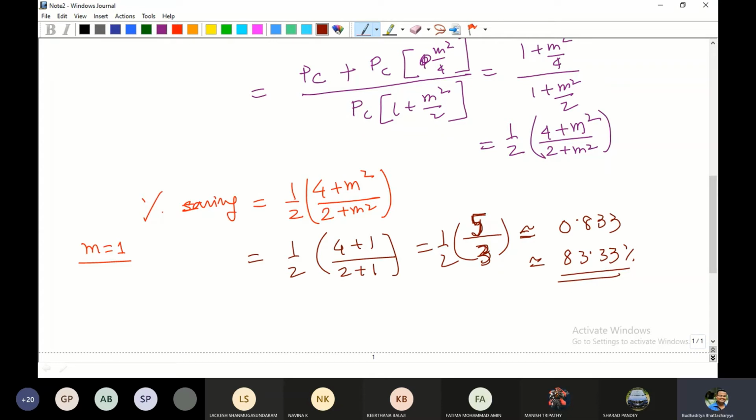Now, in the same process, for DSBSC, which we did last day, it was coming around 67%. This is for DSB I'm talking about. So for DSB it is around 67% efficiency, which is further improved to almost 83% when we are considering similar conditions. So that is why it is advantageous. I already told you about the bandwidth efficiency. It is imperative that it will have bandwidth efficiency because only one sideband is transmitted.